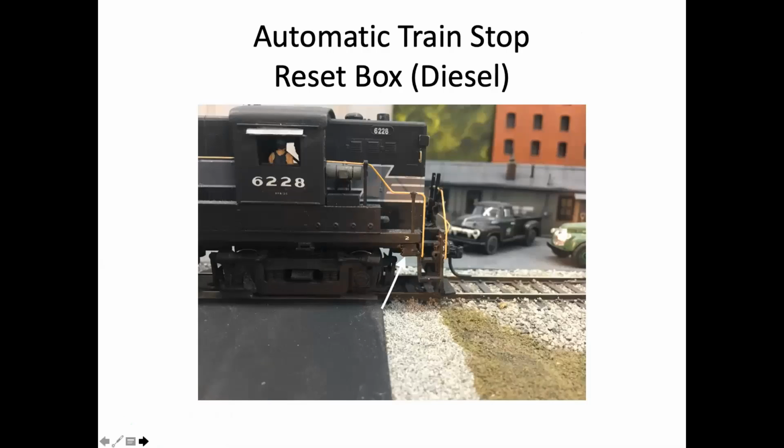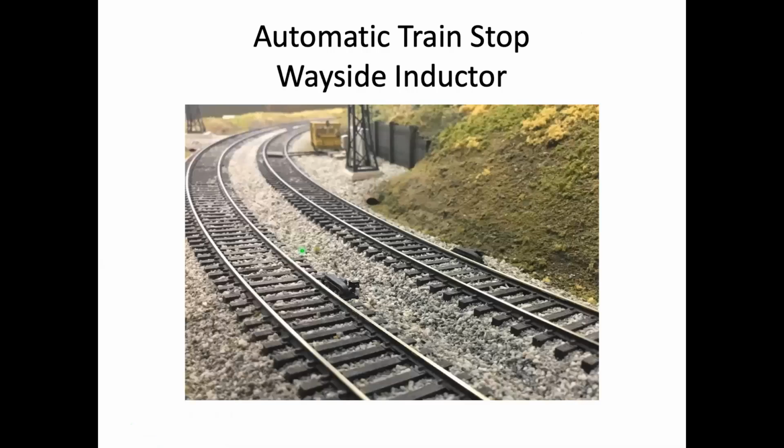And then on the wayside, what you found were these magnetic inductive system ramps that activated this automatic train stop system. In operation, the ramps, placed just in advance of the wayside signals, would be energized, and if the block were clear, the system would sound a single weep on the whistle in the cab and no other action was required. If, however, the signal was displaying anything other than clear, the whistle continually sounded until the engineman acknowledged the signal by flipping the little lever on the wall.